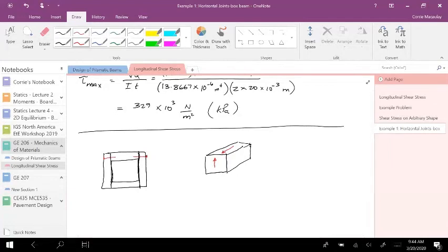But now what I'm trying to say is we also would have a shear force on a vertical face trying to rip this beam apart, right? So we also would have shear force on a vertical face. If we have that, we probably need to figure out this area on that vertical face. So now we're looking at the area, or the shear force, that's acting on that vertical face. But on our cross section, how do we calculate Q?